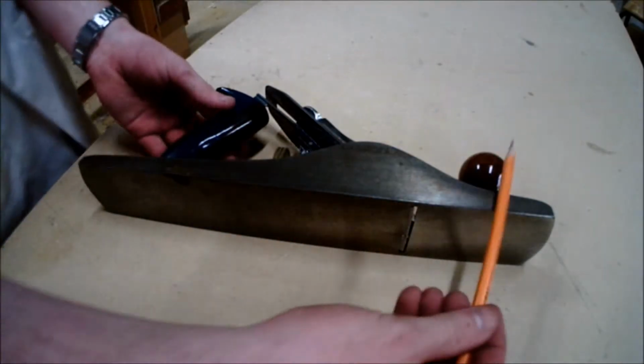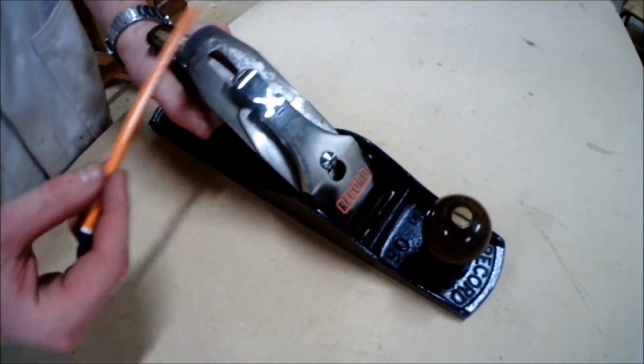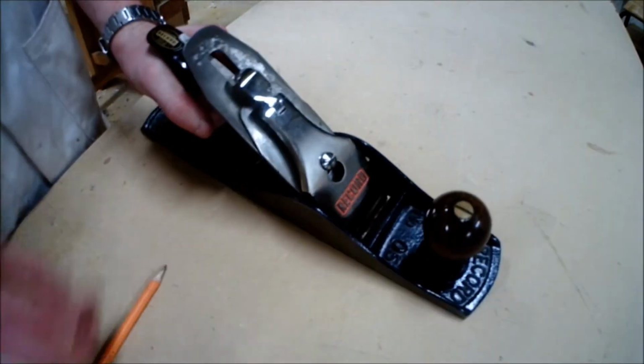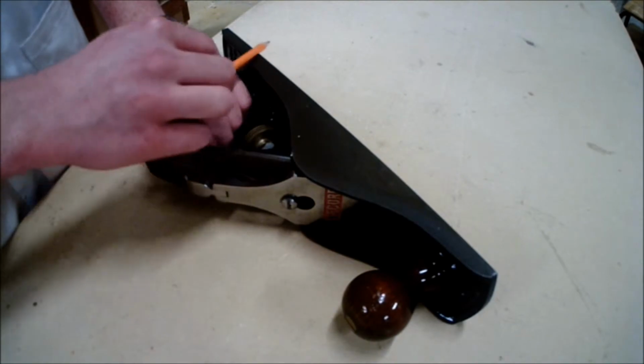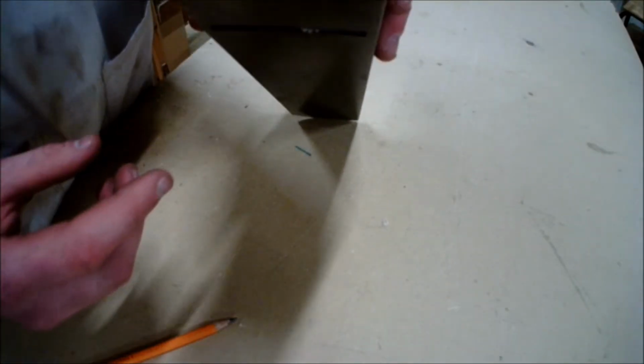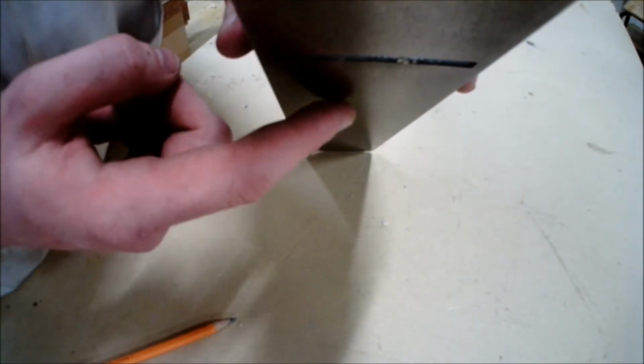The jack plane is the largest of the three planes that are most commonly used in the woodwork classroom. Due to its size, it is used on rougher material and has a blade width of 60mm. The longer the sole of the plane, the greater the accuracy in creating a square edge. This tool is used to square up rough timber.